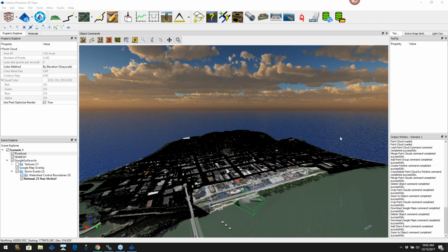The thing that we don't do with plant models is we don't create surfaces from plant models, obviously, because we have round pipes and so forth, and the Delaunay triangulation doesn't match that very well. But you can bring in the different clouds and do the editing of them, and then you can resave them out to disk for further processing.